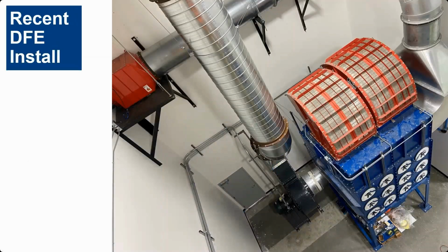And here's another one that we did. I like this picture because it shows some mitigation practices for combustible dust. This is obviously a combustible dust application. Those big hood scoops that you see on top of the DFE are flameless vents. Those allow, if there were some sort of deflagration to occur, those vents absorb that and keep it from spreading throughout the building. And then in the top left corner, you see the little red box up there. That's an inlet isolation. So should something like that occur, it detects the pressure wave change and slams shut there so that the deflagration can't work its way back up the process into the plant.